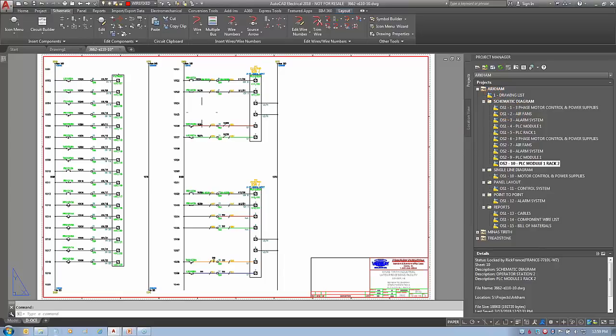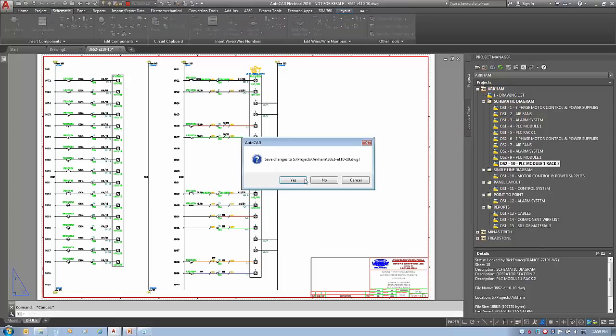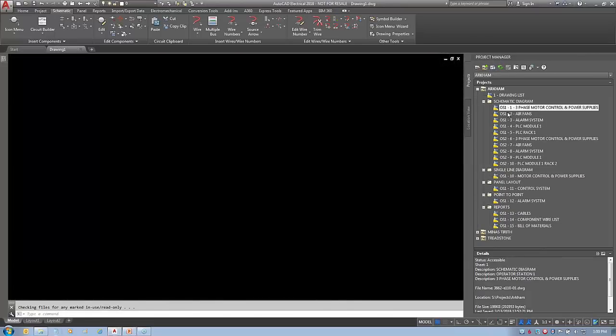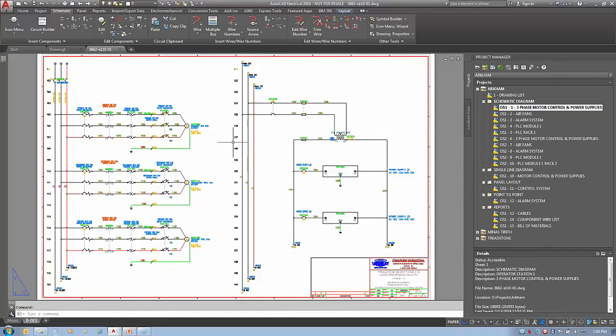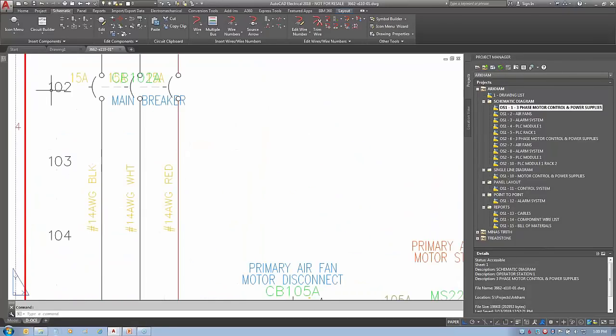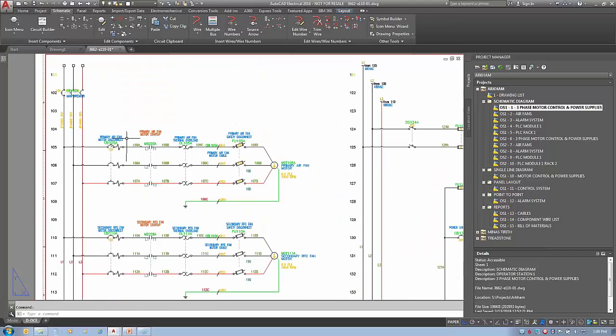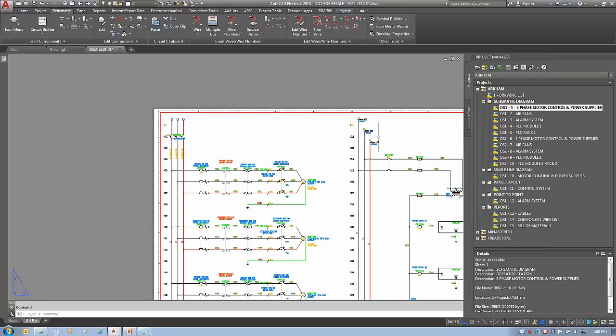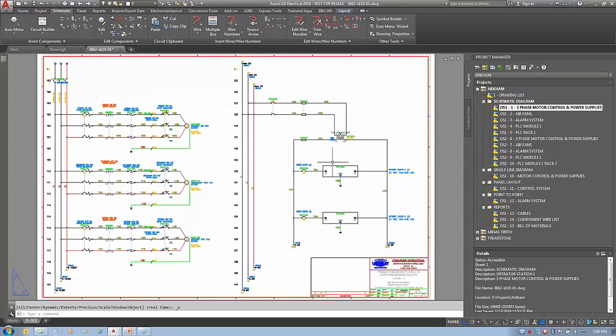sheet numbers will also, let's go back to sheet 1. Close that one, open here, because this is going to become sheet 2 because I'm using a %S%N code. It's going to fix this from sheet 1 to sheet 2. So I also want to renumber all my components, wire numbers, everything's going to be affected by this sheet number change. Now I could do that a couple of different ways. I could do it manually, but I want to use the update retag.